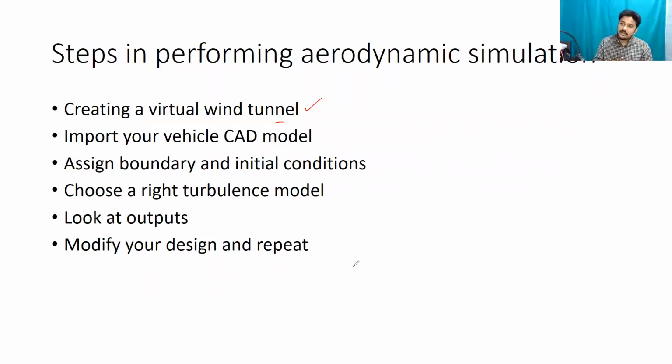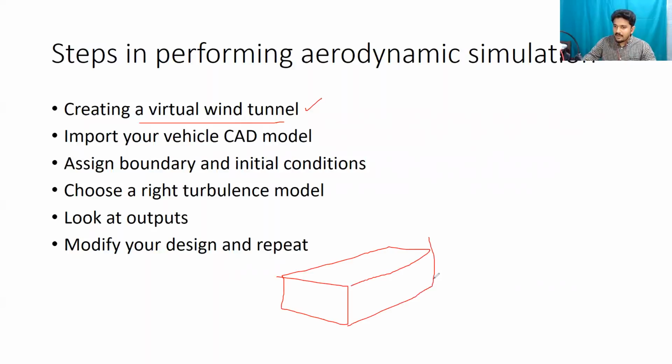A virtual wind tunnel is nothing but the same concept, but done using a computer. That's why the keyword virtual is there in front of it, right? So it doesn't matter which software you're using, this is exactly the step. You first create a virtual wind tunnel, which at the end of the day is just a cuboid. You create a huge box, and inside this box, you import your vehicle's CAD model.